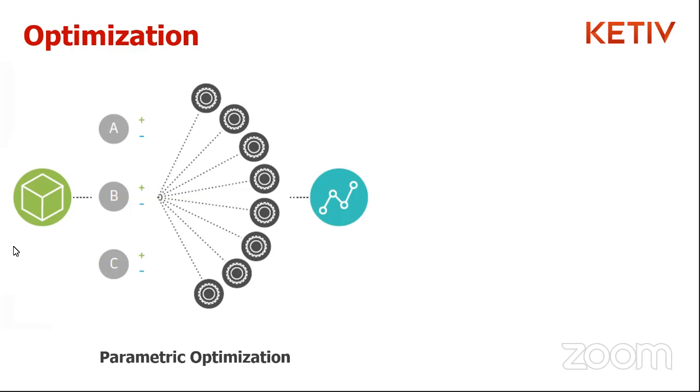It's essentially an automated way to adjust all your different factors, all your different variables, and run a series of analyses without actually changing the original CAD model. So if you want to make changes to individual parameters, individual molding settings, process settings, then sure, you'll be able to do that.